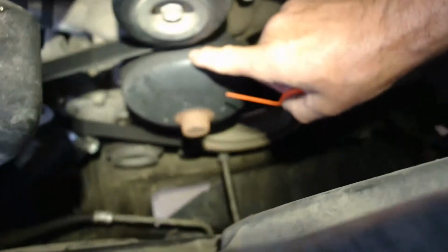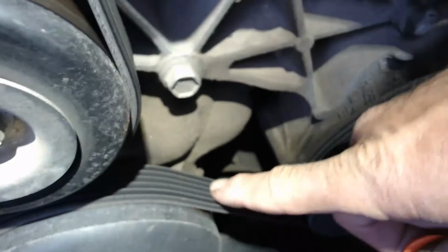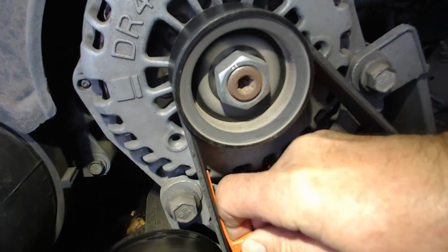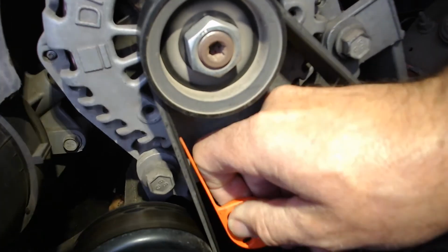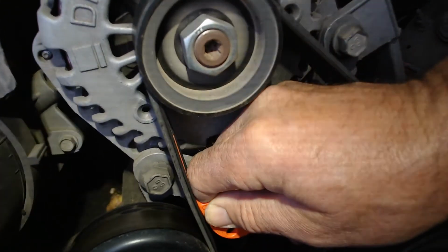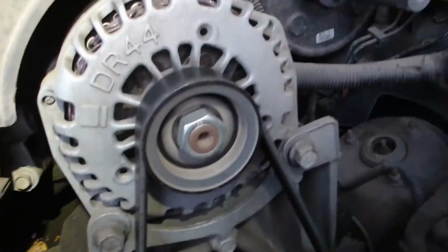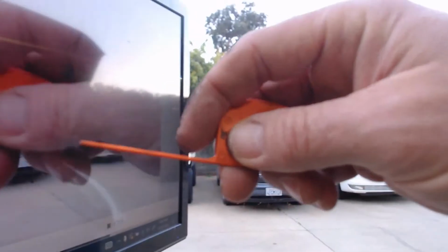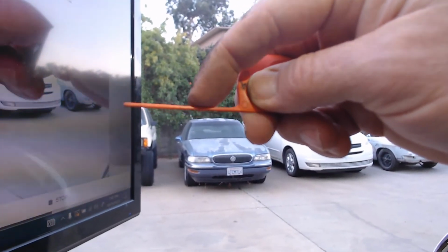But I also see some cracks down here on the belt, which some cracks are considered to be okay. The belt is pretty dry, and this is maybe a better spot for me to test it because I can get the camera on there. And it's sitting in there. Sorry, I'm having trouble doing this. No, it's down below the belt. So this belt is worn out, and we should replace that, because when you look across this thing, if it's even with the tops of the ridges, then it's worn out.